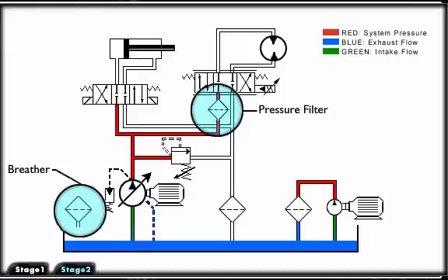Pressure filters are often required to protect the component immediately downstream of the filter, such as a sensitive servo valve, from accelerated wear, silting, or sticking. Pressure filters must be able to withstand the operating pressure of the system, as well as any pump pulsations. Return filters best provide for maintaining total system cleanliness depending on their micron rating. They can trap very small particles before they return to the reservoir. They must be sized to handle the full return flow from the system.